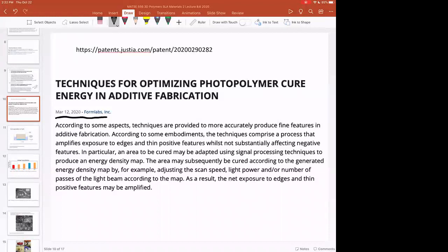And so if we think back to material extrusion AM, it's really hard to vary the temperature too much as you're printing a structure. So as you go to different layers, you can change the temperature a little bit. We'll talk about heating and other things like that. That was one of the papers that you read for your assignment. But temperature changes happen pretty slowly in material extrusion AM. But by using light sources, of course, you can change the laser power very quickly, and you can change it many, many times just by computer control.